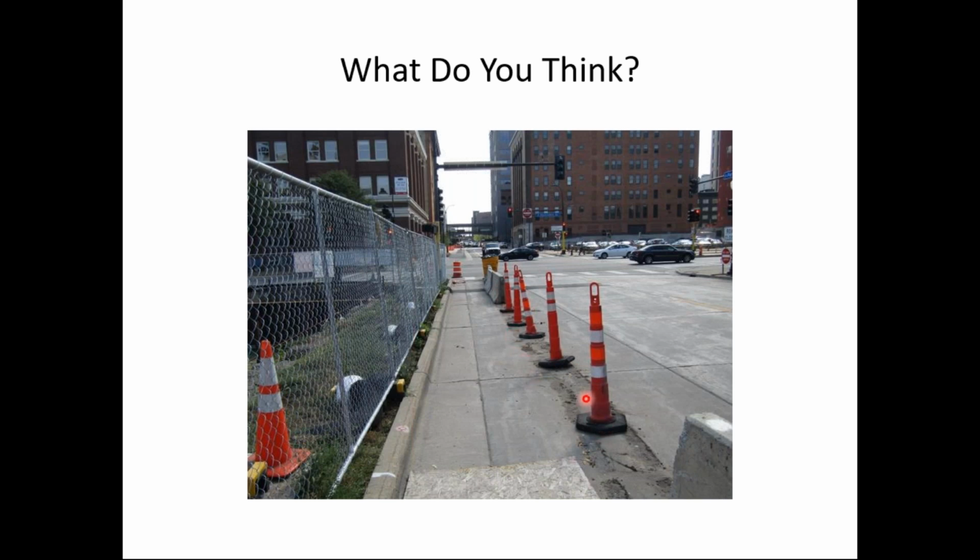But on the other hand, I would argue, notice these tubular markers, fairly widely spaced, are not a detectable barricade here, or a pedestrian channelizing device. Those of you familiar with Part 6 of the MUTCD, I believe these tubular markers are in the channelizer section, but that's referring to motor vehicles. These are not a pedestrian channelizer device. And also look at the exposed end of this concrete barrier here. Remember, traffic is coming from the back of the slide to the front. That is a potential serious roadside safety issue. If a vehicle were to depart the road and run into that exposed end, that would result in serious injury or fatality, perhaps even.